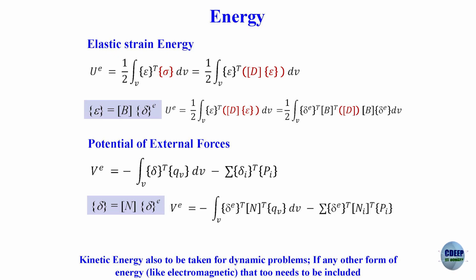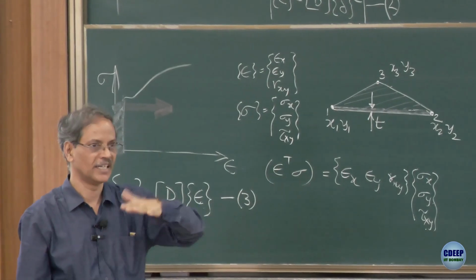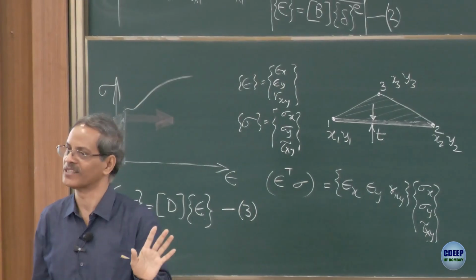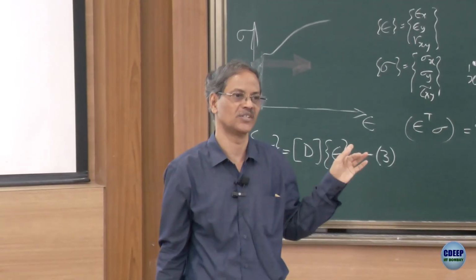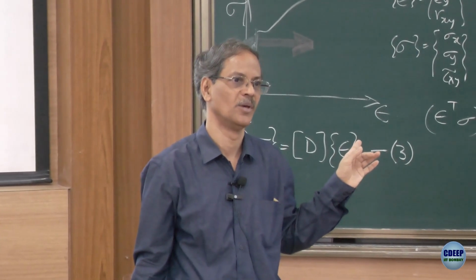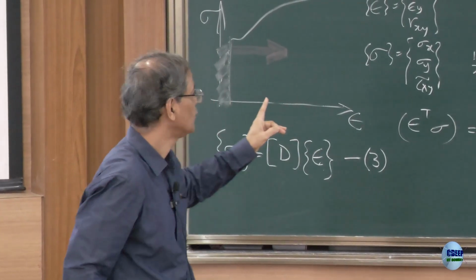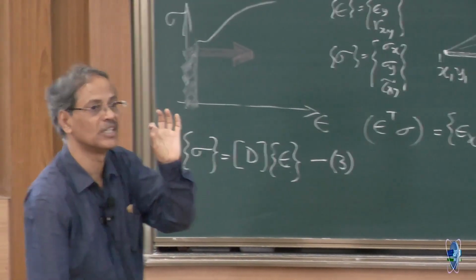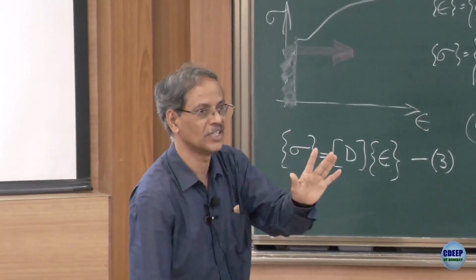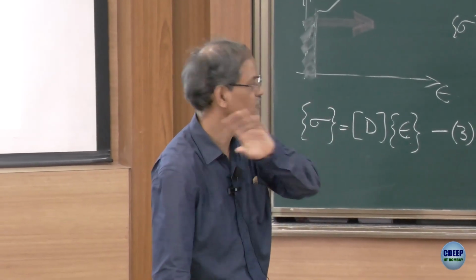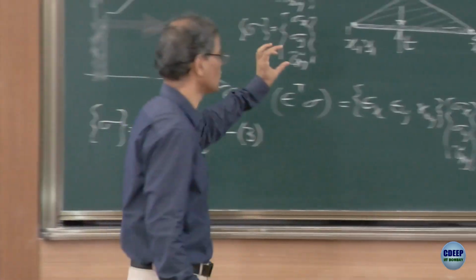In the z direction, its thickness is small and uniform throughout. Thickness does not change for us, because that z dimension is not modeled at all. In this case, it is a plane stress or a plane strain problem. So, plane stress element I am taking, with uniform thickness t. Nothing is changing, displacement, strain, stresses, nothing is changing over the thickness.